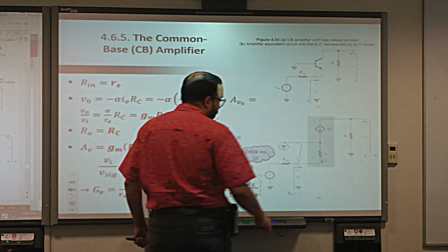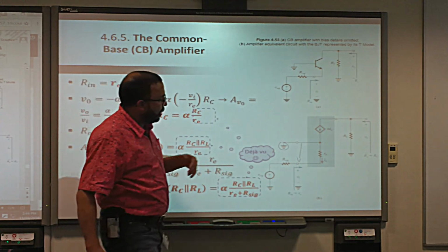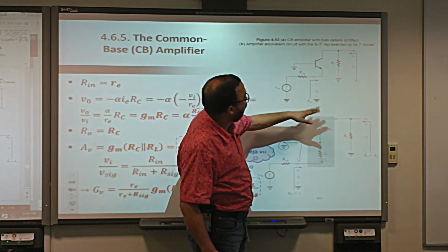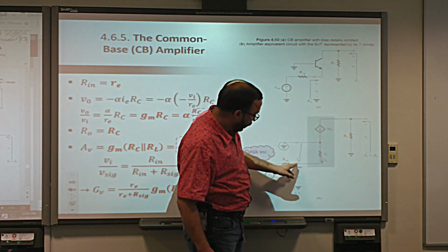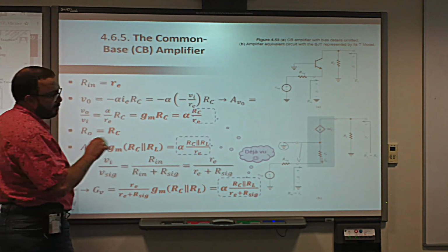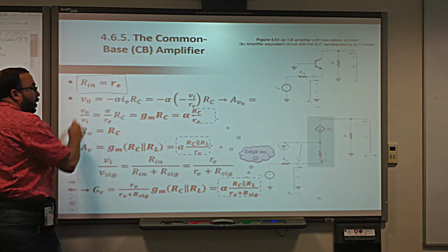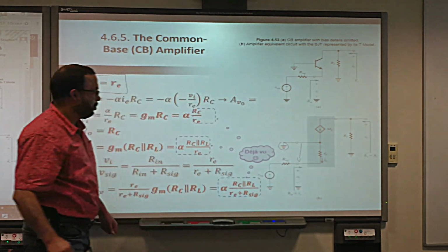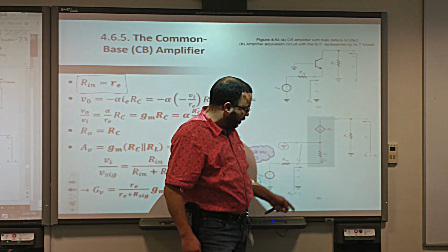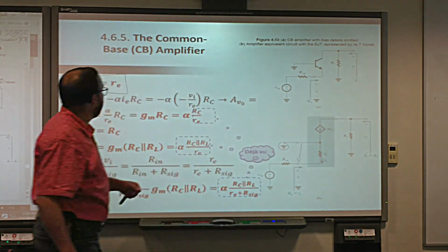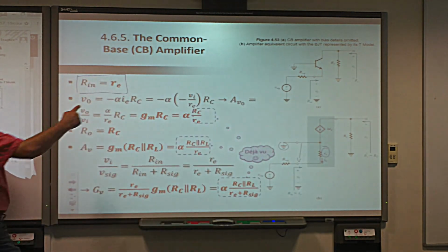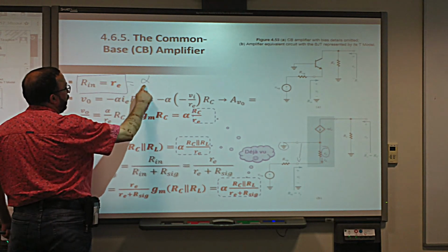But again here, there's no minus. Because basically the current that is created here is the current by the voltage; it's not coming out of the amplifier. That's why the input voltage divided by the current here is going to be RE, not minus. And the other reason also is that the resistance can never be negative in this case. So you can see that the voltage across this resistance is the same as Vin. So Vin divided by Ie is going to be only that resistance, which is RE. This resistance is, by the way, equal to alpha over Gm.